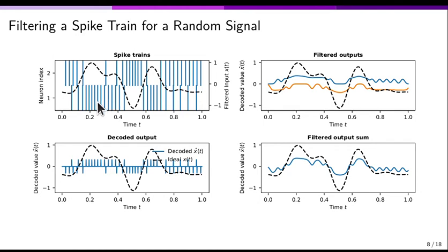Okay? How do we take a signal like that and split it up into a whole bunch of little sliding windows? That turns out to be really nice. Let's just take this input signal and slice it up into a whole bunch of different pieces. You can do that with a convolution. I can take some filter, say some sort of Gaussian blur or Gaussian window, to say how big this window is, so you don't have to have a sharp cutoff. We'll call that W for our window.